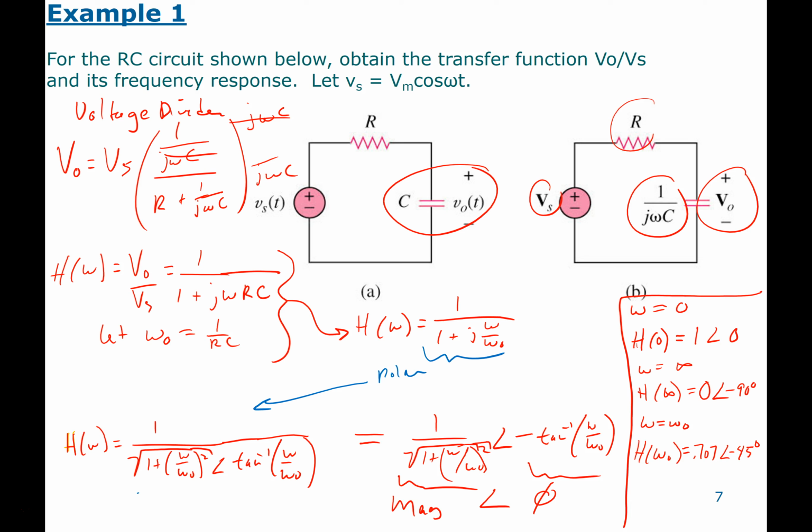And we call this a low-pass filter. Why? Well, at low frequencies it has a response close to 1, so it's going to let them go through unchanged. But high frequencies it's going to weight by a really small number, as H of omega approaches 0.